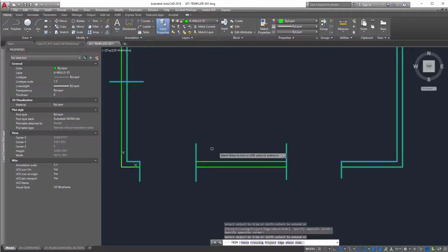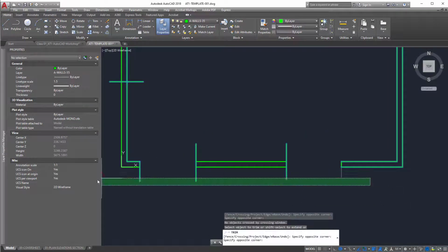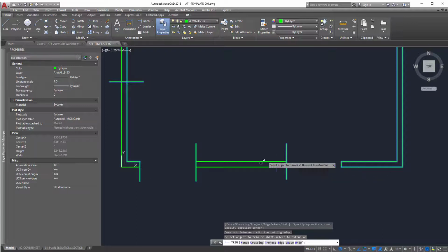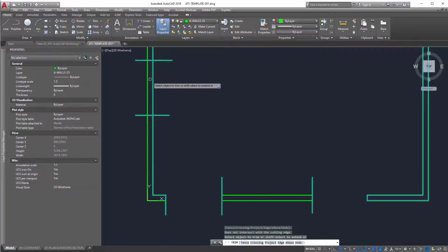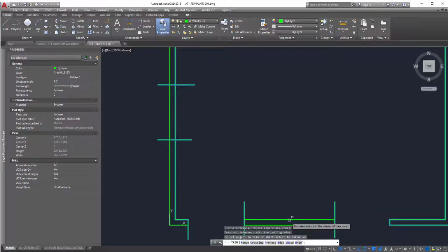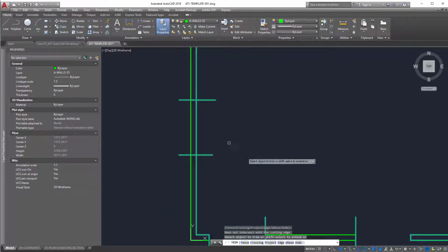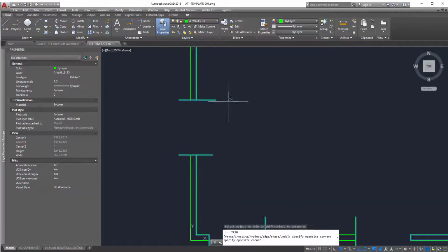I can go the other way too. I can remove these lines, and I can remove these lines. Now you can see these lines are not being removed. There's like a little no smoking sign, and the reason for that is because I've already cut them this way. These lines become deselected, so we'll have to run the command again. Same here, and you can see the slight difference in colors when a line is selected, because it's got a tinge of blue versus when they're not. I'm going to run through here.